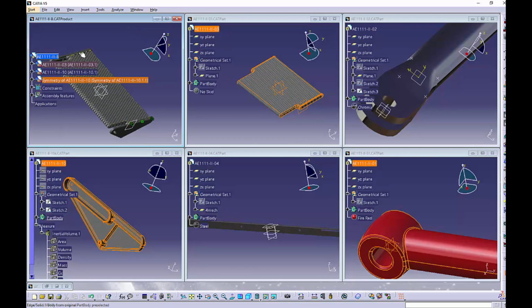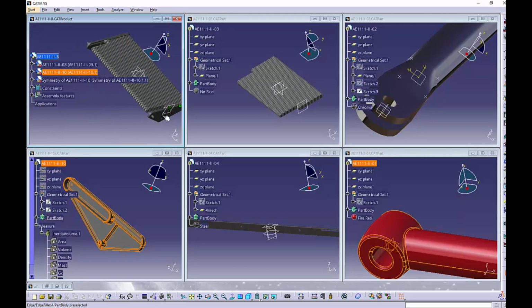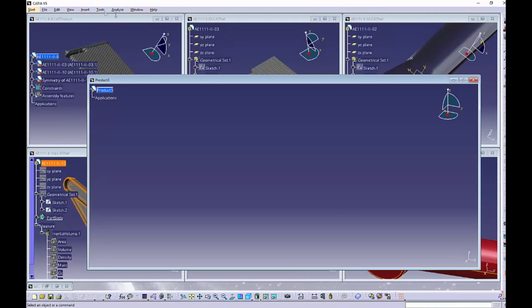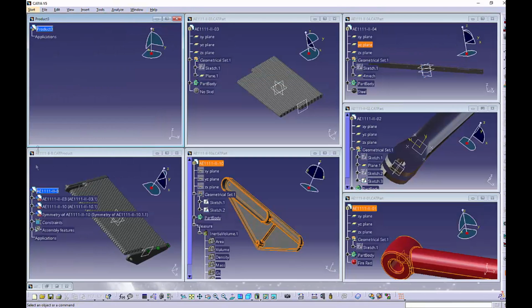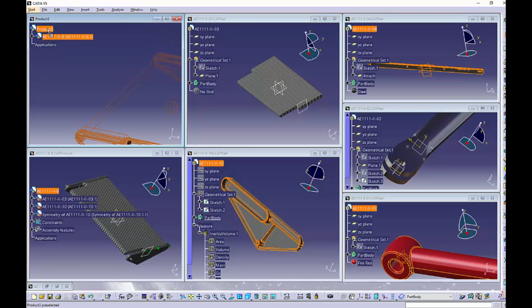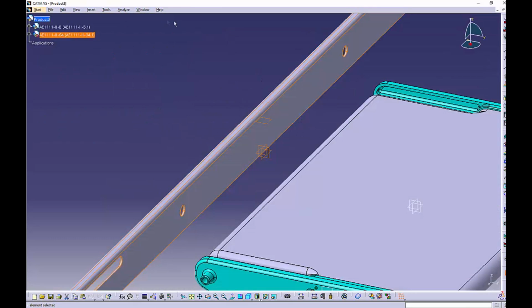We need it now. So now we have used our part number 3 and 10. We made a single step, but we want to have more stairs for our airplane doors. So we make a new product. Click again on mechanical design and assembly design, and tile vertically. And now we copy and paste, drag not part number B, but product B, to our product 3. And also the stairs frame, part number 4, to product 3. So we have both inside it, and then we can maximize it.